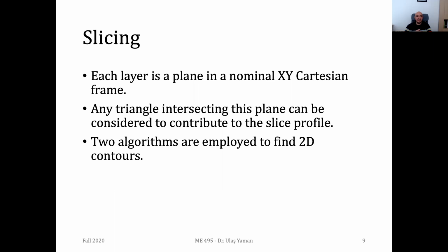And as you know, in the CAM software, after you import these STL models onto your table, you need to do slicing, since it's additive manufacturing, or layer-based manufacturing. We need to do slicing, and this is the most complicated part of CAM software. After they have the geometric shape on their table, by using the available settings, they need to obtain the contours first, and then fill the interior of each slice, and then represent them as G-code files, and these G-code files will be utilized on the machines.